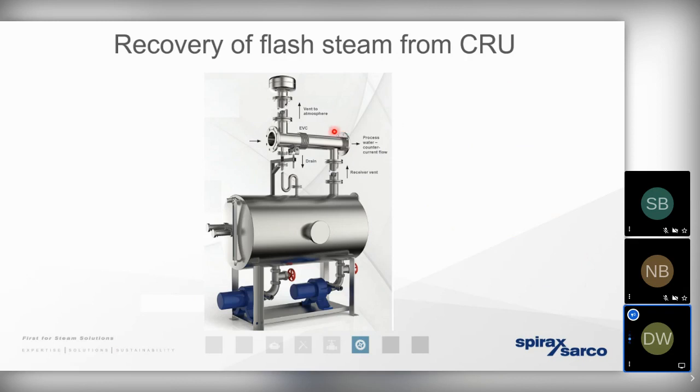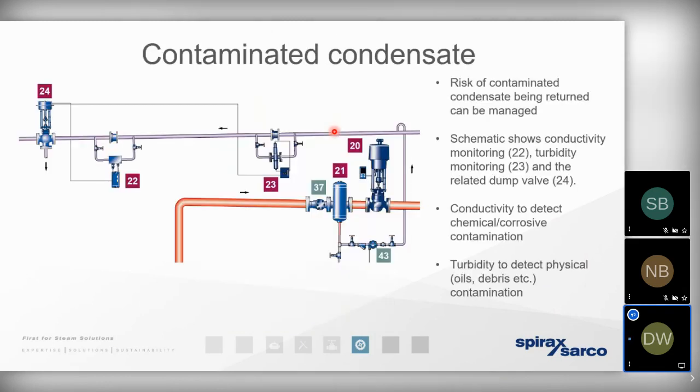add it to another process, not only are we improving the overall energy efficiency, but we're helping to keep the condensate return volume as high as we possibly can, thereby allowing for the steam condition to be held at the highest possible rate. But we also know that condensate is quite often knowingly dumped to waste through fear of the fact that we don't want it to contaminate the steam boiler, where it could cause a failure, a mechanical issue, and contaminate steam that could then be distributed out to other processes.